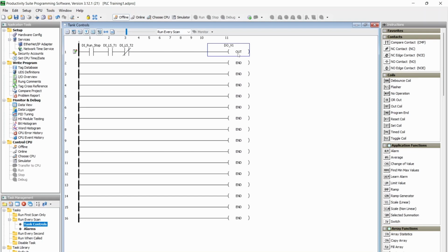So now, what else did we do here? We actually added a position switch for valve 1. Now we're going to get ready and bring in our pump. We've already given it all the conditions for all of this stuff to happen and to bring on valve 1 and hold valve 1 in. So what would happen if we're pumping down and tank 2 got full? This digital output is going to turn off.